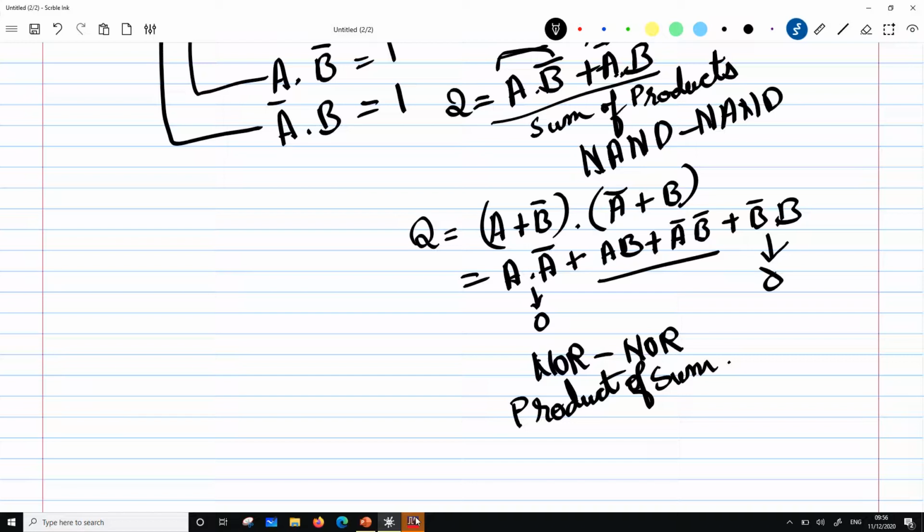So what it says is that sometimes when we represent a circuit as a SOP logic, the cost is less, and sometimes when we represent it as a POS logic, then the cost is less. And what is the cost? So for example, if I look at this XOR gate, we have got two AND gates, and then I would use one OR gate, right? And then there is the inversion or NOT gate. I will not count the NOT gate.